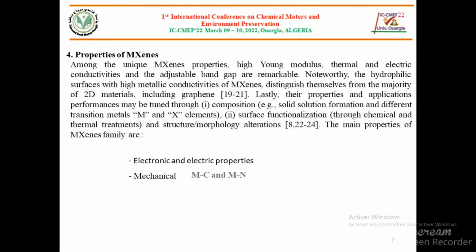Mechanical, as the MC and MN are among the strongest bonds, the mechanical properties of MXenes also attracted great interest. The first simulation study has suggested elastic constants C11 at least 2 times greater than MAX phases and other 2D materials. However, despite the C11 values being 2 to 4 times lower compared to graphene, their bending stiffness is higher, which